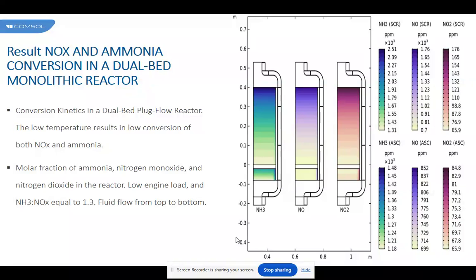As high cell density monoliths tend to have a lower thermal mass, their use has been proposed to reduce the light-off time. When cell density is changed, a number of other properties, including the fluid distribution, are also affected. So it is necessary to include all of these effects in a model.